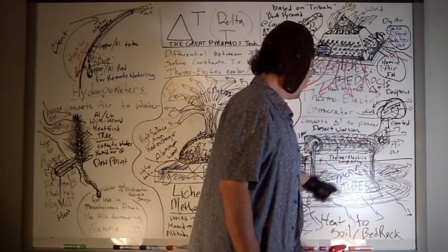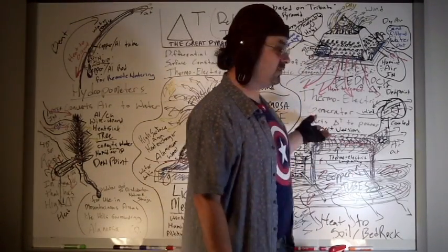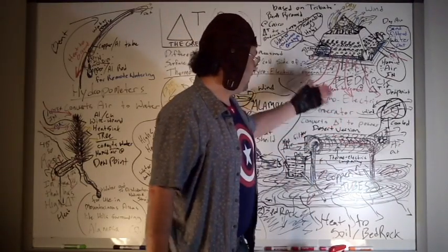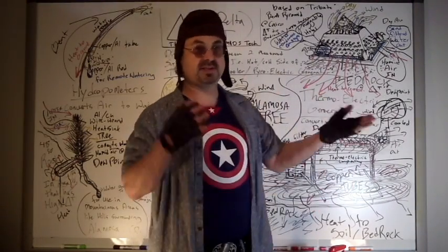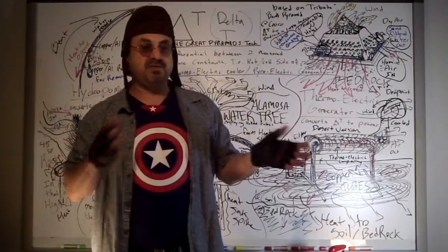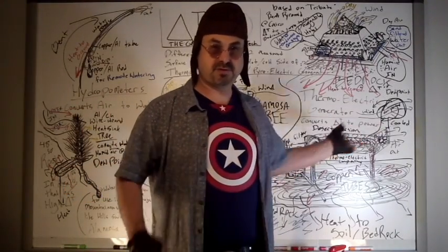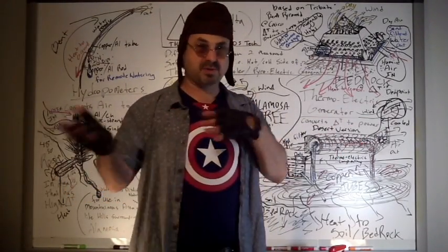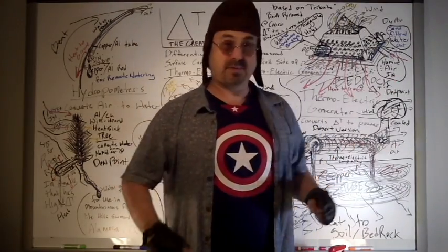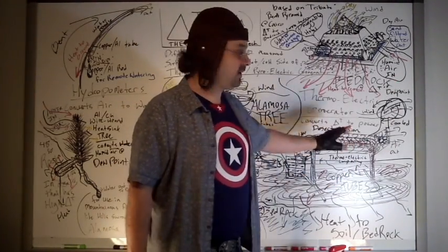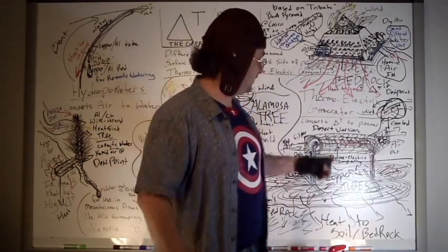And what it does is it has the temperature differential. Now this is only going to work in some places where it's hot on the surface and cooler in the ground. There's going to be a delta T. I think it needs to be at least 15 degrees delta T for the thermoelectrics to produce the highest amount. But of course, the hotter you get, typically, the better they work. So that's to get free power and free air conditioning in the desert. That's pretty good too.